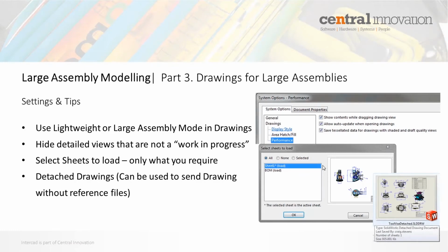Okay, so the first tip that I'd have here is that you should be using lightweight or large assembly mode in drawings. Last webinar I covered the fact that we can use those modes in the assemblies themselves. What you may not have been aware of is that you can actually use those modes in a drawing.